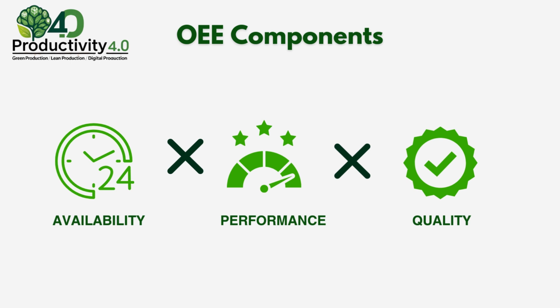Availability refers to the actual working time of the equipment within the planned time. A machine that stops due to malfunctions, adjustment time, or die changes reduces this rate. For example, if a shift is scheduled for 8 hours of production, but there is 1 hour of breakdown and 30 minutes of die change, availability significantly decreases.